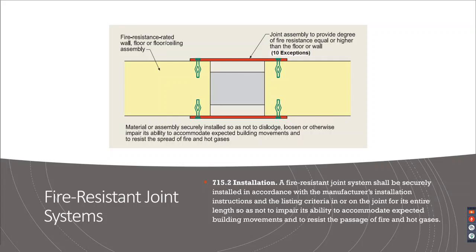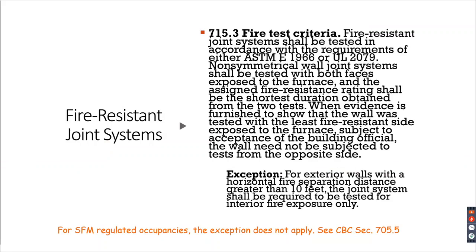It is installed, of course, in accordance with the manufacturer's installation listing, but also the manufacturer's installation requirements, and that's for its entire length, of course. So it doesn't impair the ability to accommodate expected building movements and to also resist the passage of fire and hot gases.